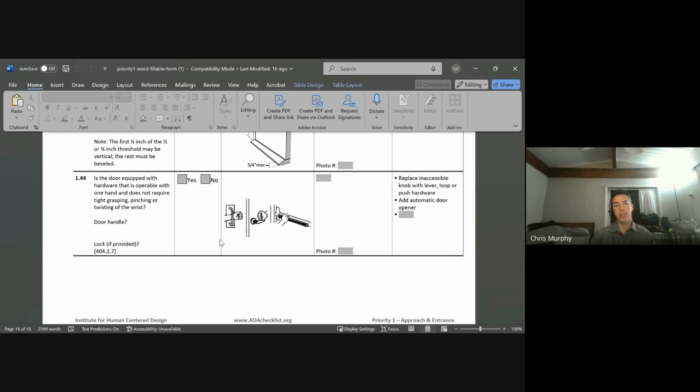That is a possibility. It's more of a Title III issue that you can relocate parking spaces to further away places, and that potentially could happen for Title II. But it's just something to be aware of: you're really looking for your slopes, essentially. If the closest parking to the front entrance is on a slope, but there are parking spaces a little further away that are not on a slope, and there's an accessible route that complies with accessible route requirements, that could be your best option for providing program accessibility.